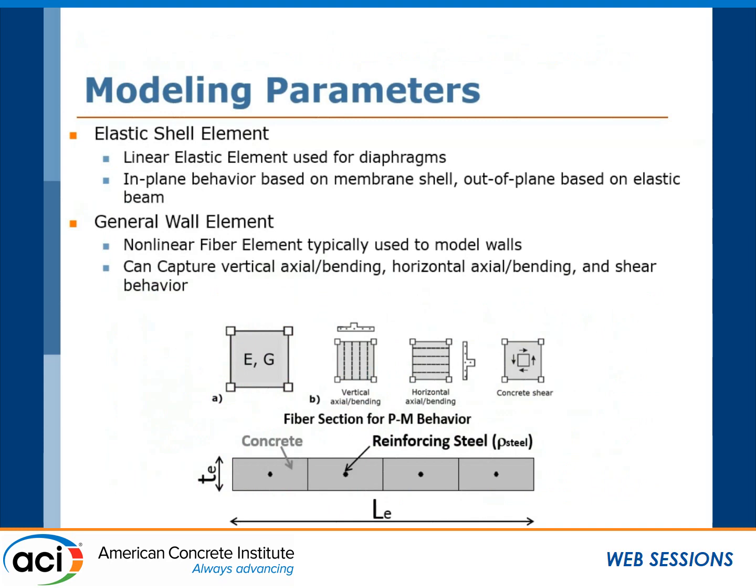Over here is an explanation of the different element types we used to model the transfer level. The linear elastic shell is a linear elastic element. It's typically used to model diaphragms. In-plane behavior is modeled as a membrane, while out-of-plane behavior is based on elastic beam.